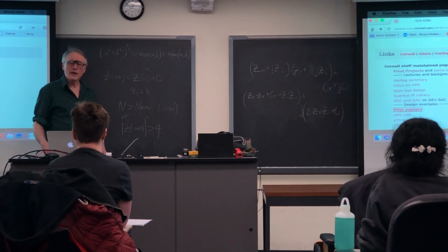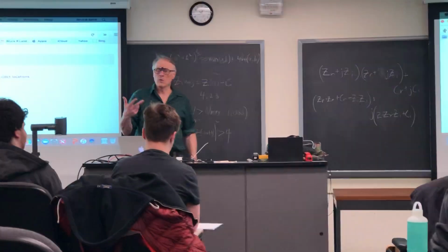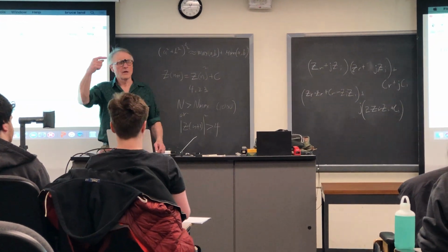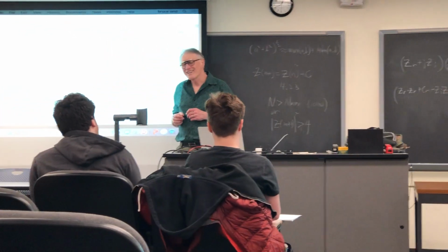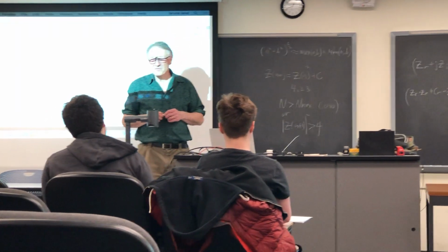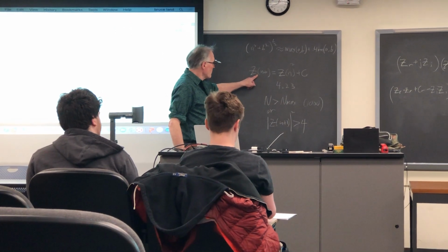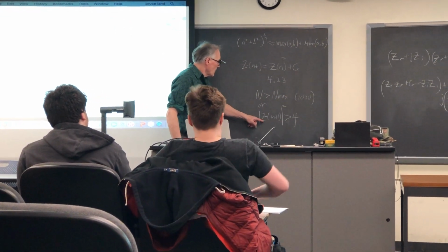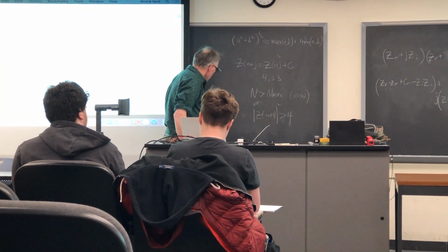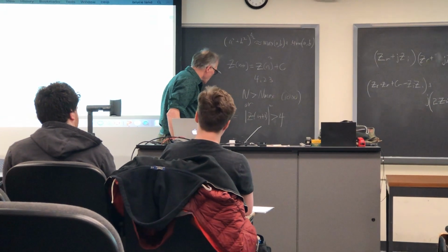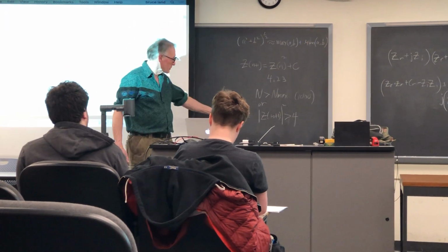So, 5 multiplies takes 2 cycles, you have to do these, then this. Or use 1 multiplier with a 5-state state machine. Yes. So why doesn't computing the magnitude of Z n plus 1 squared also take 3 multiplies? Because it took 3 multiplies to compute Z n plus 1 by squaring Z n. This is equal to Z real squared plus Z i squared. That's the magnitude of the complex number, 2 multiplies.